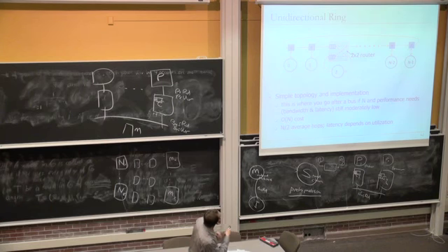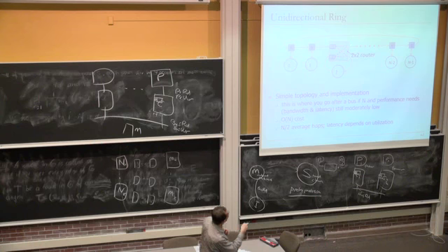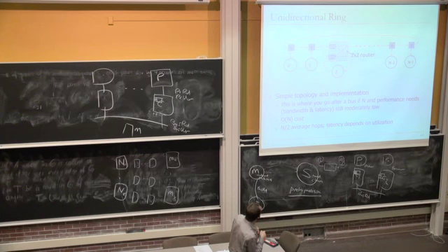So if you look at a unidirectional link, this is simple, right? The router that you need for this is the node. The node needs to be able to inject into the ring, and the node needs to be able to eject from the ring. That's why you have this crossbar that's needed, or 2x2 router. So this is just to give you a lower level look into what you need to have. And you could also, of course, optimize the design of this to be simple.